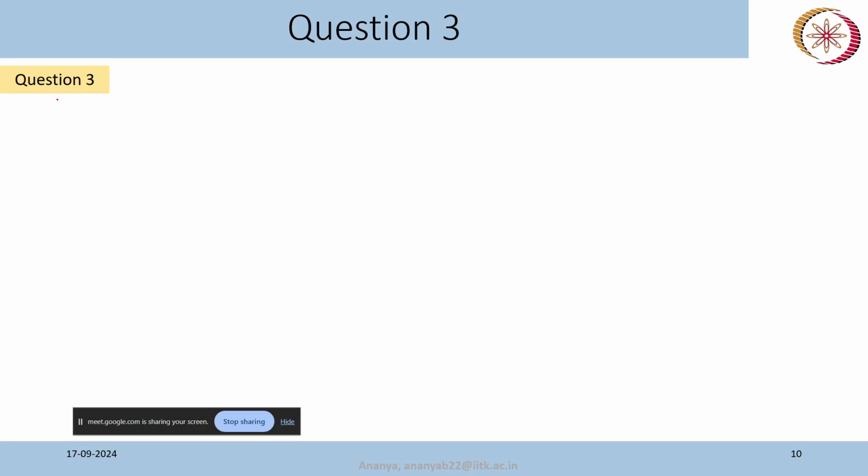So what will be the output voltage for minimum temperature and maximum temperature? At minimum temperature, R2 is equal to 20 kilo ohm, right? So V out will be equal to 20 by, what is this value? This is also 20, so this is 40, multiplied by 20, so this will be 10 volt. Okay.